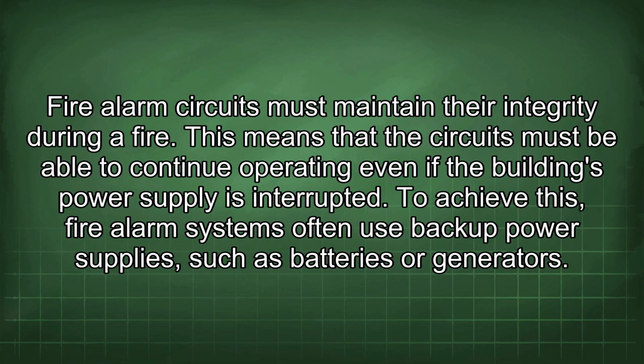Secondly, circuit integrity. Fire alarm circuits must maintain their integrity during a fire. This means that the circuits must be able to continue operating even if the building's power supply is interrupted. To achieve this, fire alarm systems often use backup power supplies such as batteries or generators.